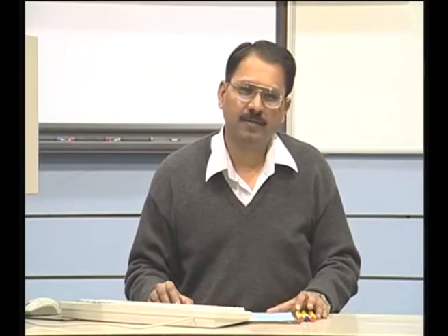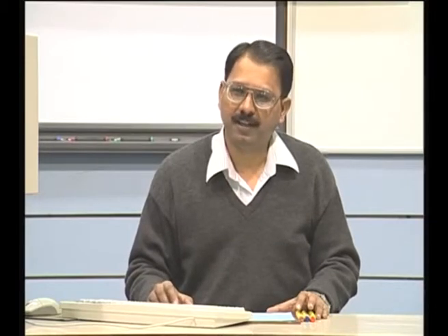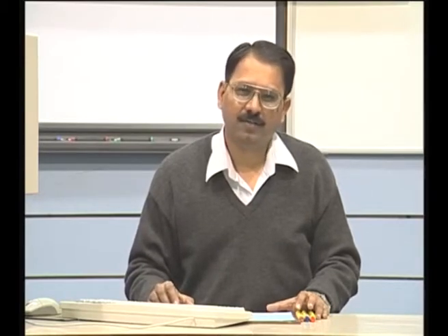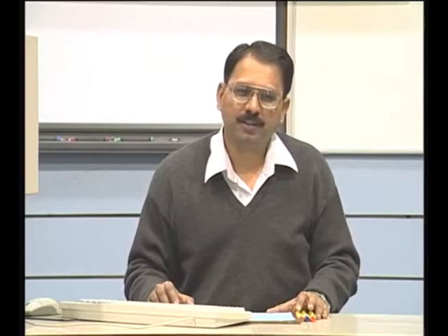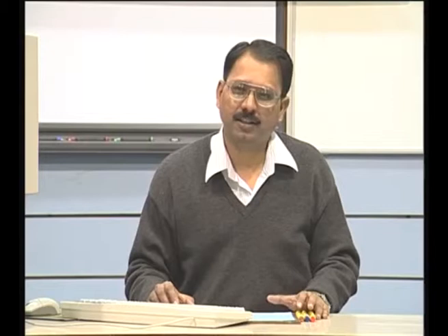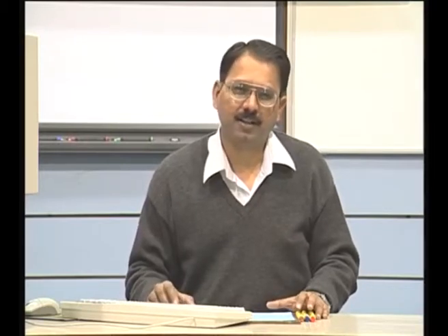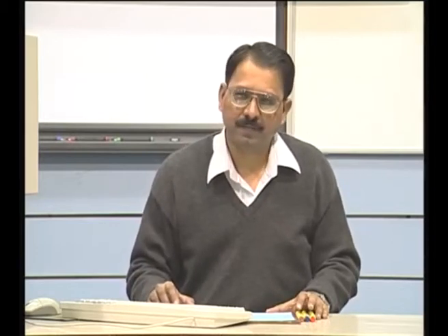Ideally, we do not want terms like u to the power of 9 or higher order. We have also seen that a cubic, that is u cube, serves the purpose of most of my applications, because it gives me both slope continuity as well as curvature continuity, and beyond that is not of much importance.